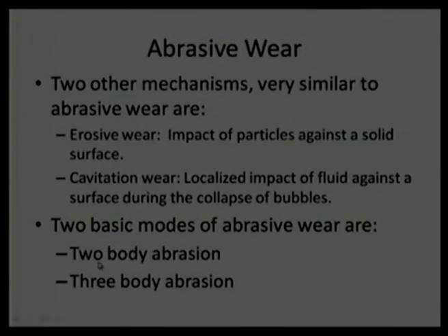Experiments show that two body abrasion is causing slightly higher wear rate compared to three body abrasion. And then, maybe again subjective, many times we have observed that three body abrasion causes only 10% damage compared to two body abrasion. So, a number of parameters are going to affect it: particle shape, particle size, everything will matter when we talk about the abrasive wear by three body abrasion phenomena or mechanism.